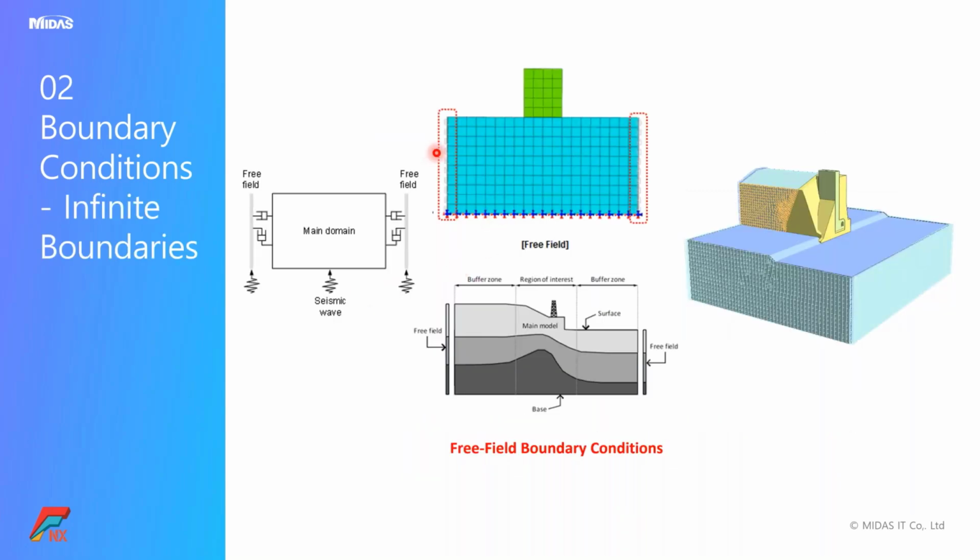Firstly, infinite medium. As I said, there are two kinds of boundaries, but one is the absorbent boundary. What happens over here is whatever wave is generated at the base travels to the top, basically the surface waves. The vertical boundaries, which are absorbent boundaries, will just absorb it when the wave is reaching near the boundary. So it's not transmitting to the infinite medium, but it's just absorbing it. Then it might not be correct in all the conditions because of the following.